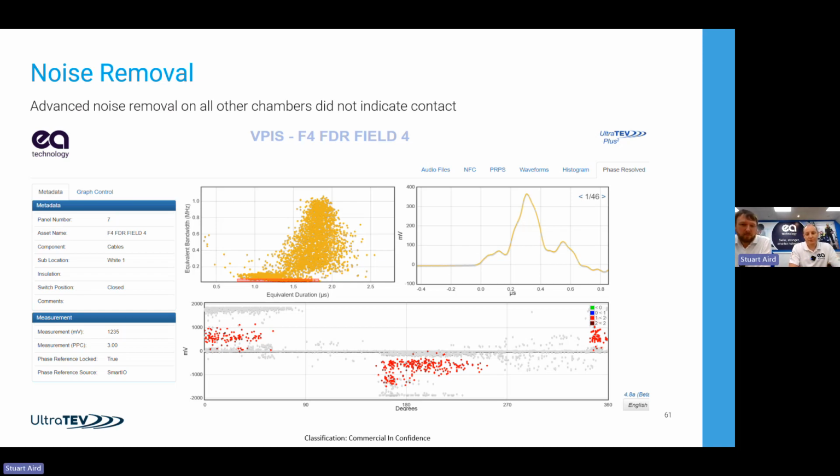Yeah, okay, so there is, and thank you for the question. We do provide permanent monitoring systems that can be either permanent or semi-permanent. If you know you've got an issue and you want to trend or manage that gear, we can install it temporarily. It just magnetically clamps to the outside of the switchgear, so it can be done with the system fully live, and we'll cover your cables, your switchgear and your transformers. Equally, that can be a permanent monitoring system with all the data back to the cloud, and we can manage that service for you. So definitely something that can be offered. Generally, compared to a handheld device, it's got a slightly higher cost, and you'll be using it on your more critical assets. Thank you.